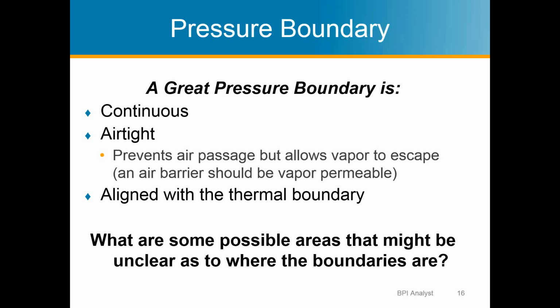It could cause problems where if the vapor went all the way through the wall or through the roof, no big deal. But if it condenses somewhere inside the wall, then we're going to have a buildup of bulk moisture, and it's really hard to dry out a wall or any enclosed assembly in the building. So that's part of the problem with the air leakage. And then of course there's drafts and stuff, which makes people feel uncomfortable. So just bad all around.